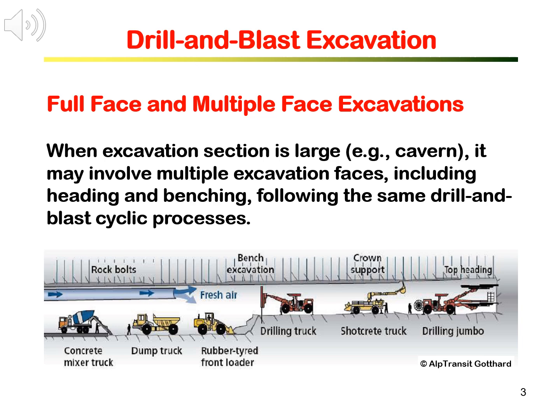The size of the excavation phase is governed by several factors and needs to consider the overall efficiency of the cyclic process. In general, for small to medium size with area below 80 square meters, that is about 10 meter diameter, full face blasting is usually preferred.